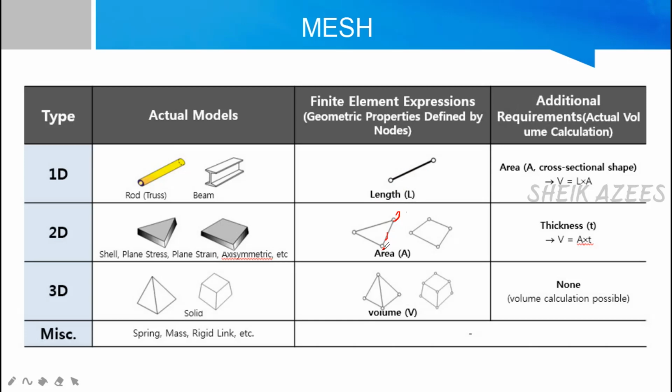For 3D there are cubes, that means hexahedral or hex-dominant, and tetrahedral. Like when we have a cake and cut it into small pieces in a cube manner, it is called hex-dominant. And if we cut in a triangle shape, it is called tetrahedral. So these are the meshes majorly used while doing the modeling. I can clearly explain how it's performed. Here I show some examples so that we can clearly understand how it's performed.